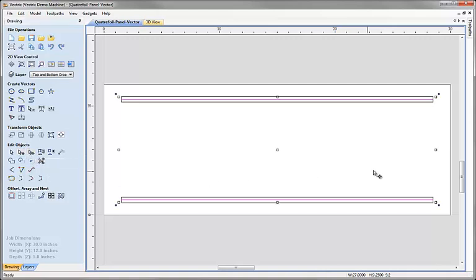That'll go into the transform mode. You can see I get the drag handles on here, and then holding the shift key down, so I'm scaling from the center of the vector, I'm going to click on the end and just drag this out a little bit so that I come out past the edge of those rectangles. So it may not be necessary, but it's just going to ensure that my tool is going to completely clear the edge of the part once we do the cutout pass.